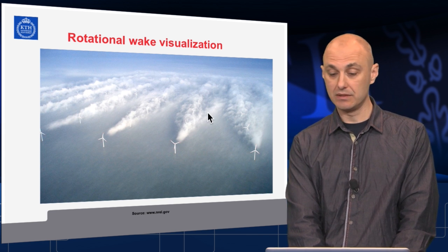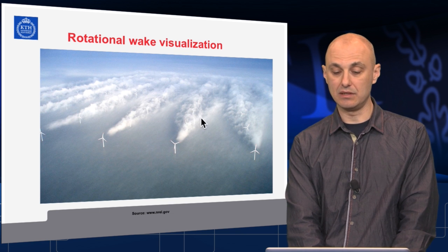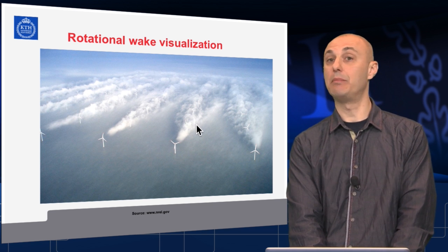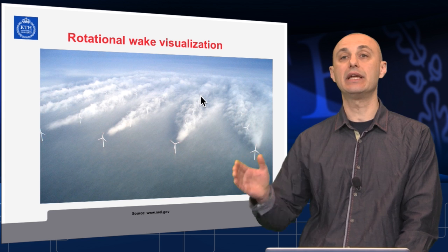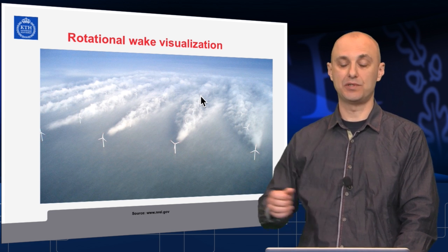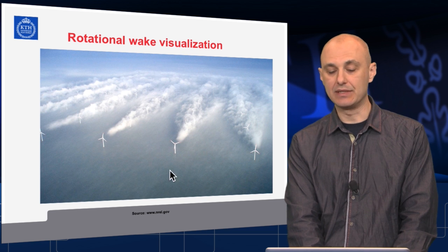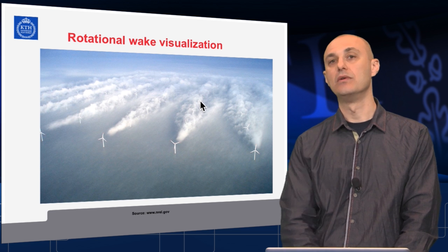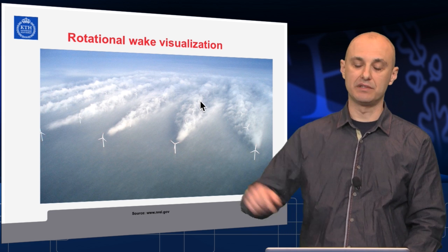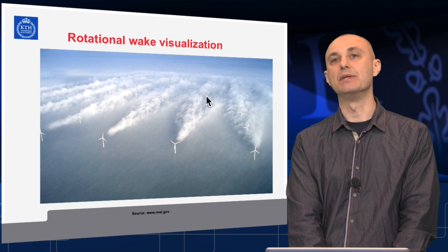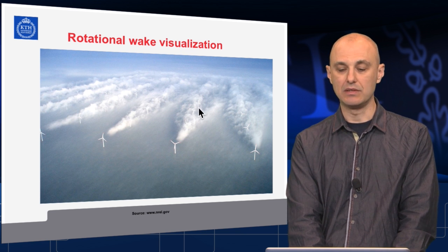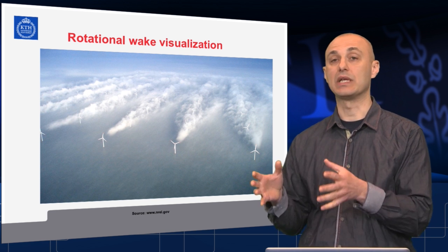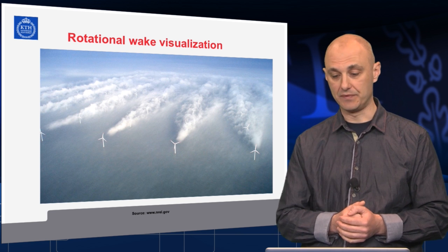Turbulence starts to appear towards the edges at the boundary layers. And in this particular case, unfortunately, it hits directly the next row of turbines, something that should not happen. It has happened here that the wind comes from the most undesired direction, directly along the row within the matrix of the wind park, along the row of turbines. So each next turbine is severely obstructed and unproductive, working inside the wake of the turbine in front.